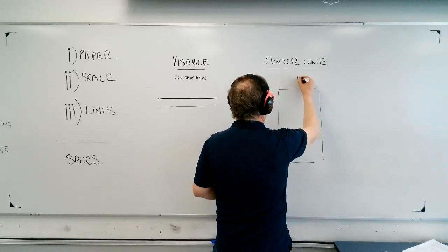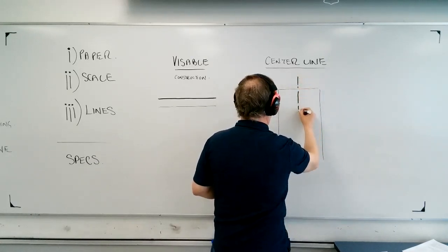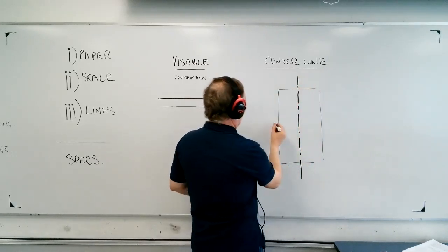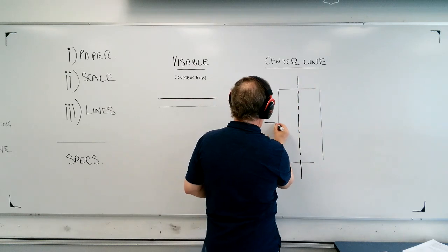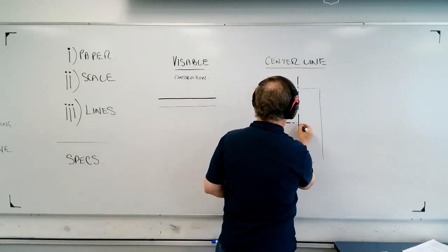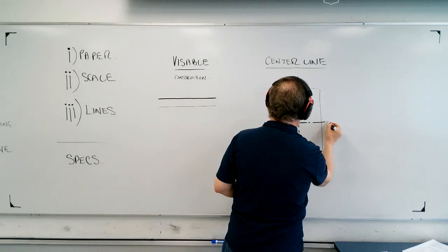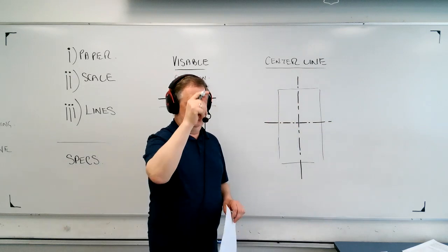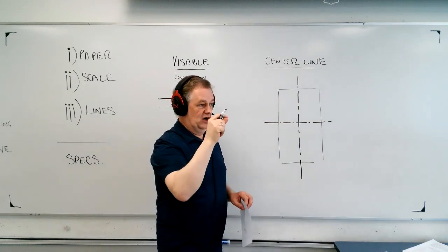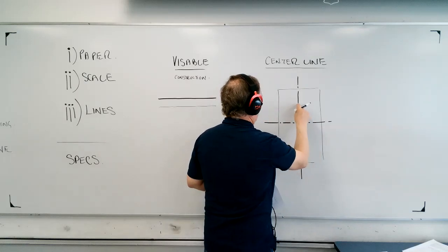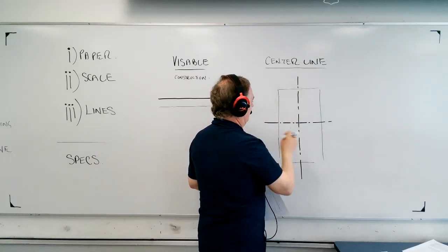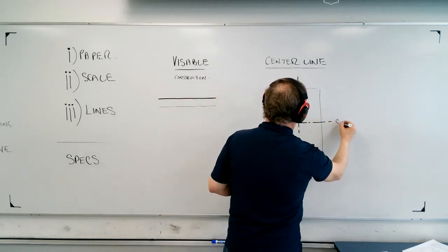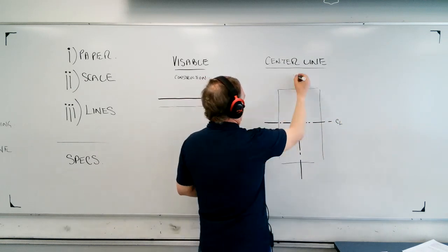And what I'm going to do is go like this, and I'll draw one this way too. When you see that line, it's an alternating sort of a dash and then a short bit. A long and a short dash put together like that indicates a center line. Sometimes you'll see this written, CL, but not always.